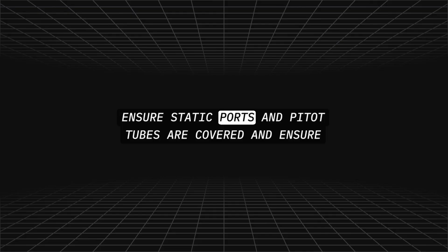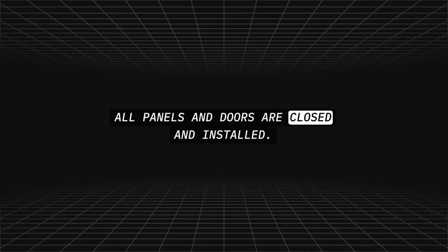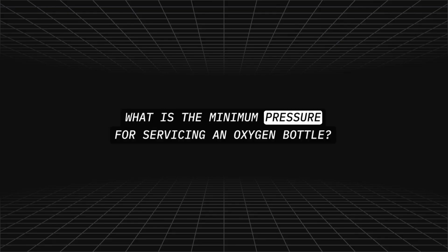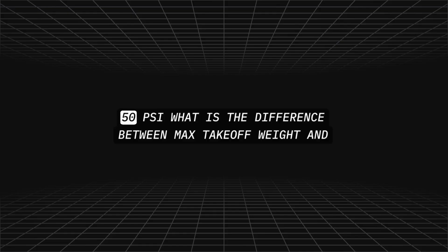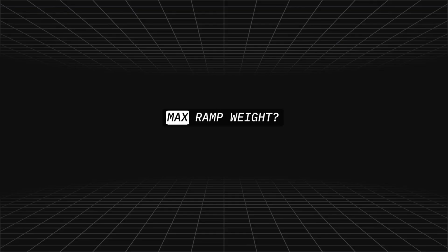Ensure static ports and pitot tubes are covered and ensure all panels and doors are closed and installed. What is the minimum pressure for servicing an oxygen bottle? 50 psi. What is the difference between max takeoff weight and max ramp weight?